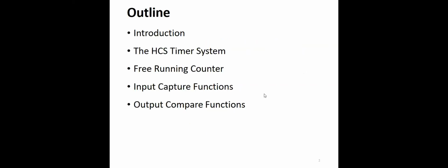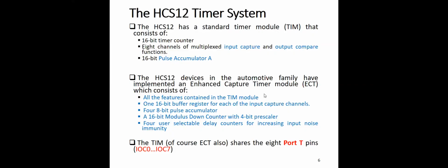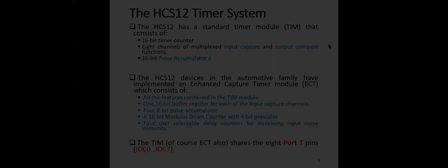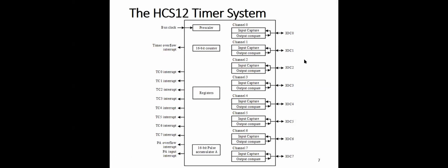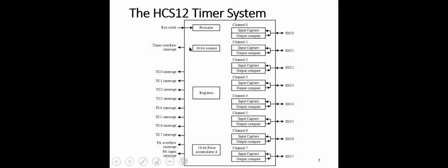So basically, we started discussing the timer module or timer function that is available in the HCS12 microcontroller. We started looking at this module, which is the TIM module. If we look at the block diagram, at its core there is the 16-bit counter, which is connected to the bus clock.